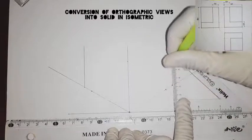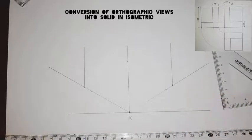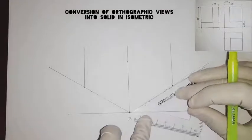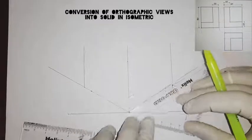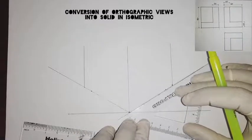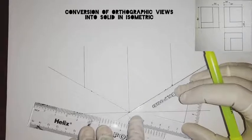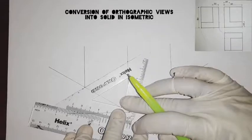So this one, now remember, because we are not using the two set squares that are supposed to be used, we are just going to draw this line to be parallel to this other side, because this line is 30 degrees. If we could have used the two set squares, the 30 degree set square could be easier, but still you can still draw a parallel line from there, beginning from here.